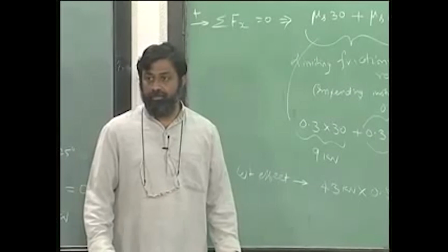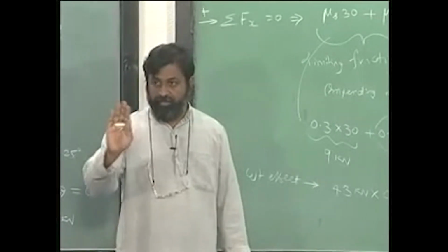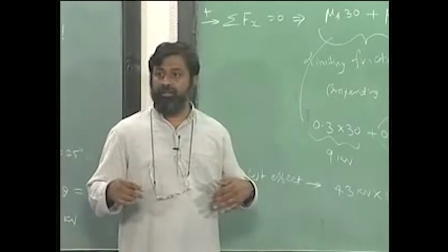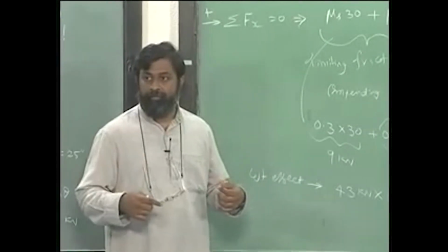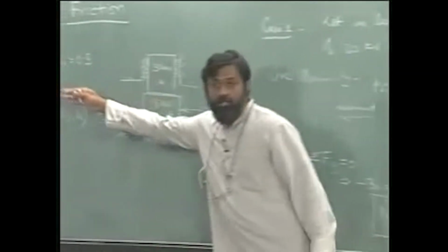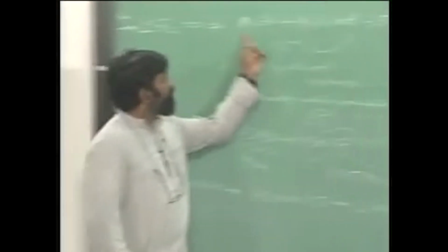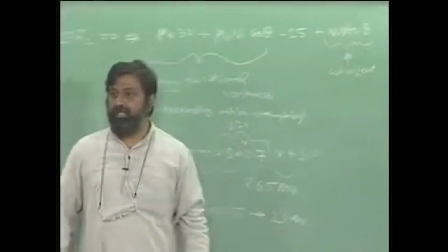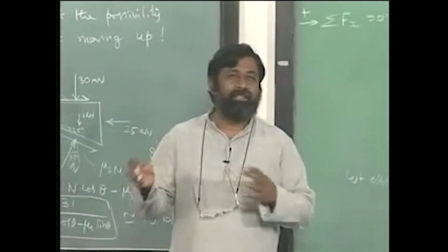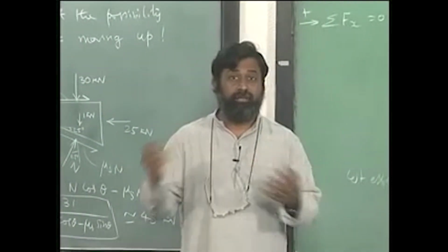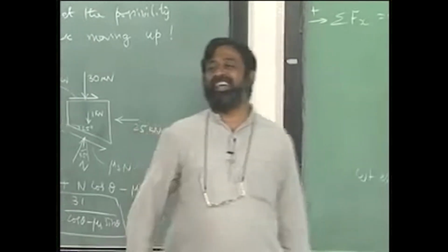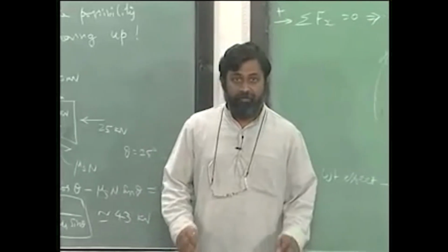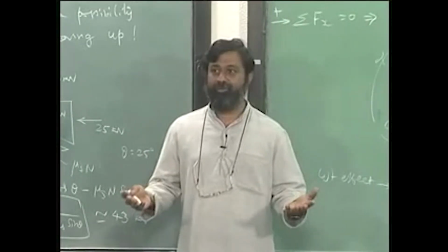And if I have to think of a resistance, resistance will come in terms of, for example, if I have to push this all the way like this, the resistance will come from this and the weight effect. So I have to offset 18 plus roughly 18 again, or let us say 20 plus 20, I need to have at least 40 kilonewtons in order to push this guy. I have done a very rough calculation, but it is very useful to me now.